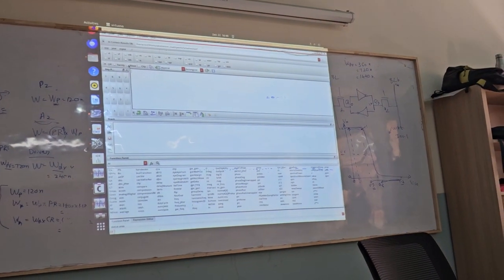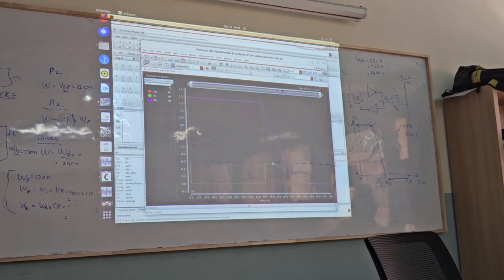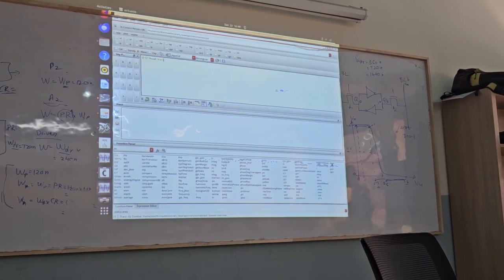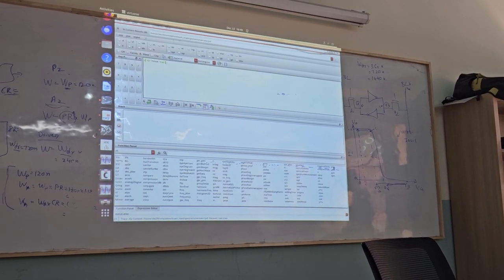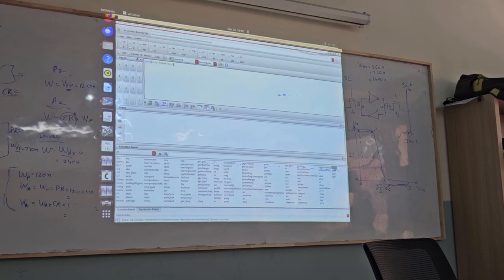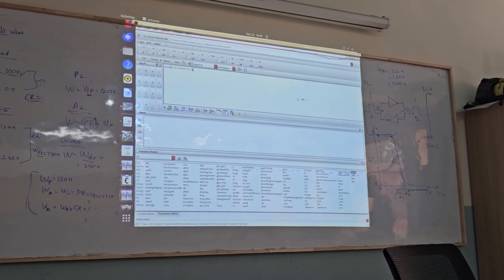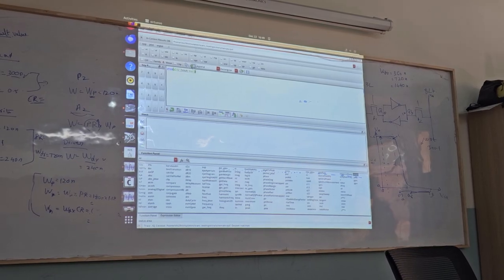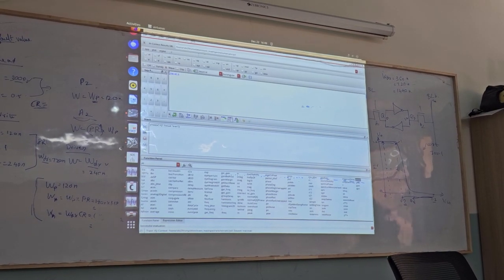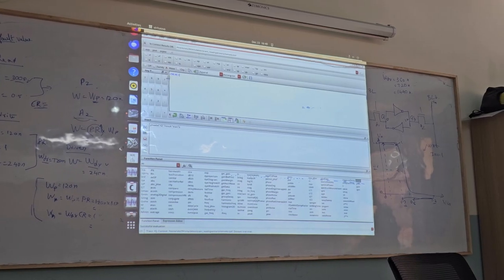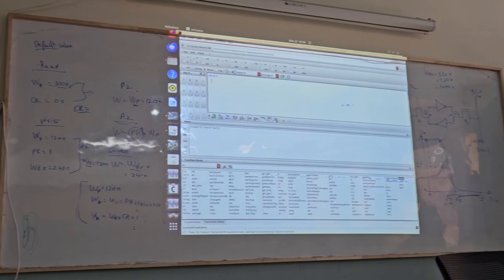And now choose wave, radio button, go back here and select the Q wave. And then there is a function from the function panel, which is the Y max. To select that Y max, so that in turn will apply the function onto the wave that we have selected. And when you evaluate, it returns us a value that is close to 300 millivolt. Okay. So now our task is to reduce from 300 all the way to 120.